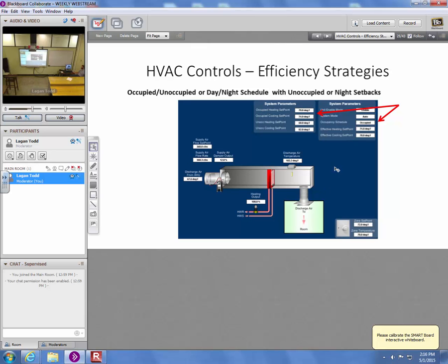And then if the thermostat down here compares current room temp to set point and says it's too warm in here, we need cooling, it opens this damper and brings more 65-degree air into the space to cool it. Conversely, if it looks at the current room temp and says it's cooler than set point, we need heat, it keeps this damper at minimum, and it starts to open this heating valve on this reheat coil that flows hot water, and it raises the discharge temp of the air coming through and heats the space.